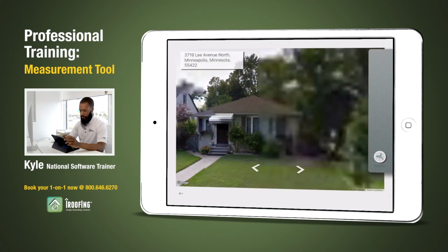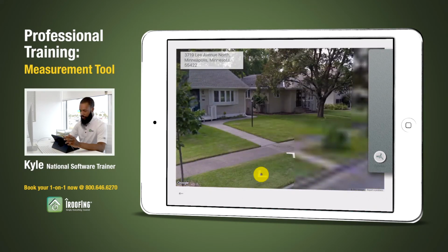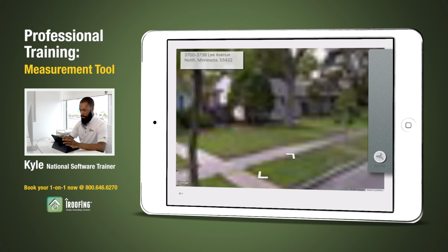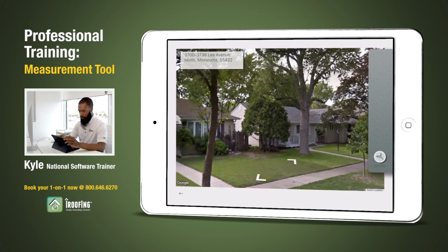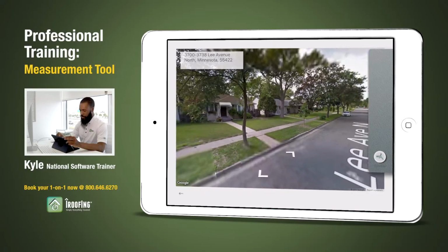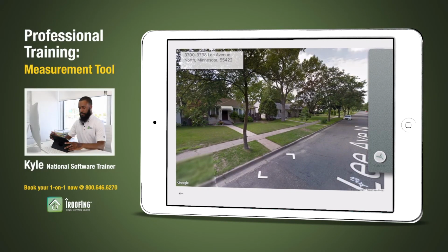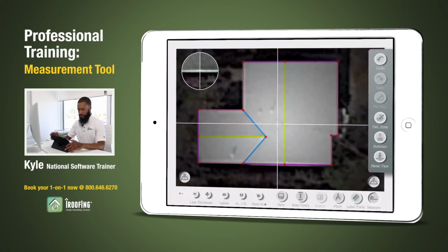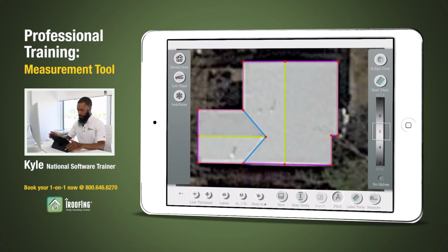If I use the arrows at the bottom of the screen, I can navigate down the street a little bit, look over at the angle between the rakes on the roof, and I can see that with this particular roof, we're looking at a pitch of about a 6/12. Now I'll hit the back arrow in the bottom left corner, tap on pitch at the bottom, select the number 6 over to the right, and then tap my finger within each area of the roof that I would like to set as a 6/12.